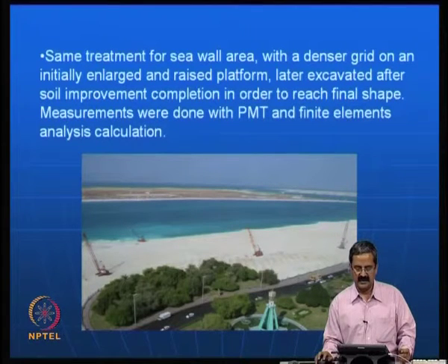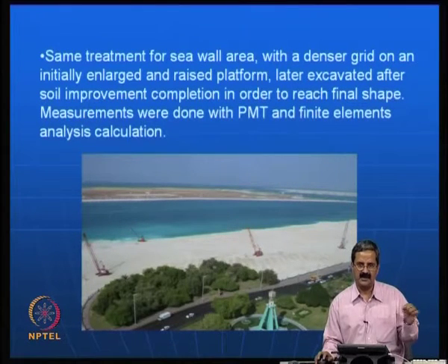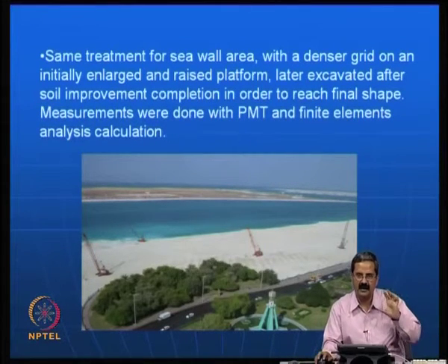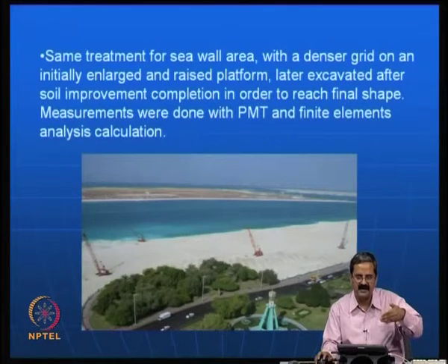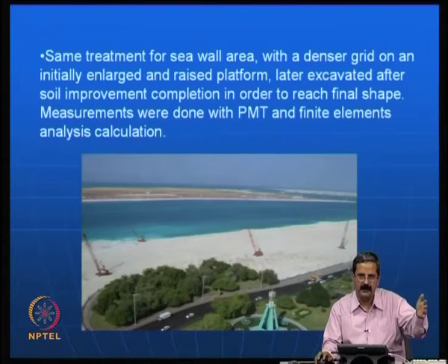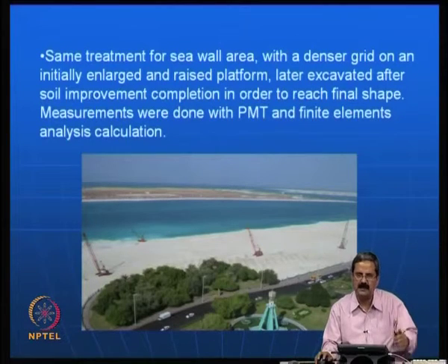And so this technique, we are able to see the design, like we have used a simple method in which you can design based on the weight available. You can design the height of drop and the spacing, and for the required depth of improvement. Actually the depth required depends on, say for example, you say that 2B is a significant zone. Say for example, you have a footing B, 2B is the significant depth of pressure bulb. So one must be able to calculate the significant zone.